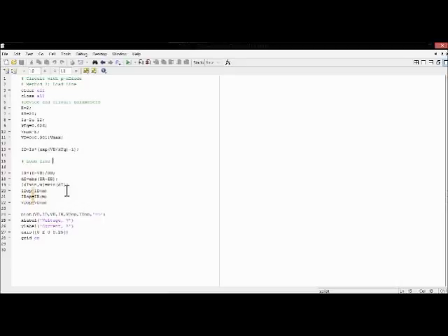And now for the graph, for the load line, we have IR equals E minus VD by RB from the circuit diagram. You can refer to the circuit diagram, and similarly all the values have been entered. At last we have plotted all the graphs, with the X label given as voltage and the Y label given as current, and we have also assigned an axis. Now this keyword grid on is used to apply the grid on the plot. So now we will run this.